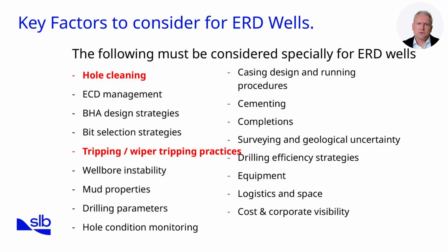Tripping practices must also be carefully controlled. In horizontal wells, wiper trips don't clean the hole, and excessive backreaming risks destabilizing the wellbore. Wellbore instability and mud properties must be addressed in tandem. Inhibitive mud systems, correct rheology, and chemical stability are all vital.